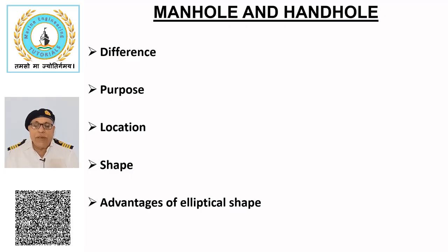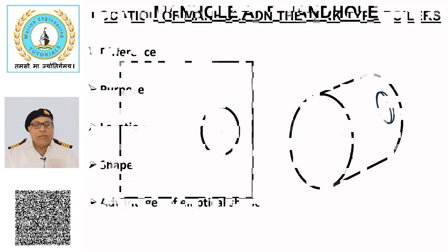The elliptical cover is fitted in the boiler from inside where steam assists to close it. Studs are not subjected to steam pressure, thus they can be made lighter. For the same reason, dogs need not be highly stressed and the nut can be tightened just to prevent steam leakage.